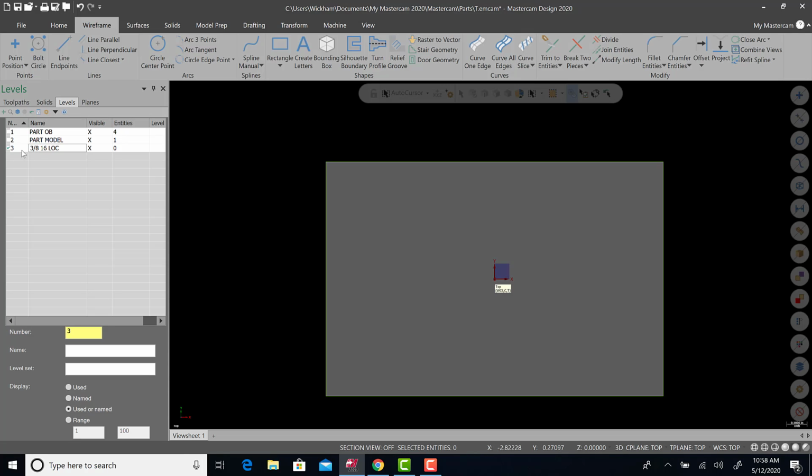So now that this is there, I know it says it's active. I always right click and make active, out of habit, because sometimes the parent, as far as like we're going to offset this over, the new line will be in the same level as the parent, which is fine. It happens. There's an order of operations here that needs to occur. I've had issues where if all the levels aren't on, the levels won't get put there right during the actual offset, which we'll fix. So I'm hoping that it actually does happen, so I can show you that. Again, levels are just for your organization.